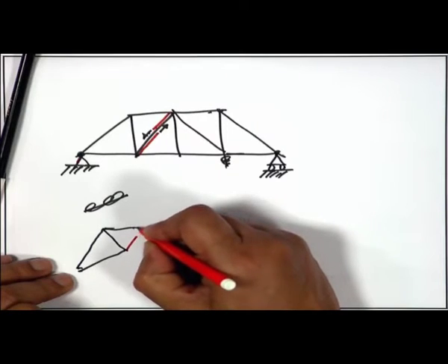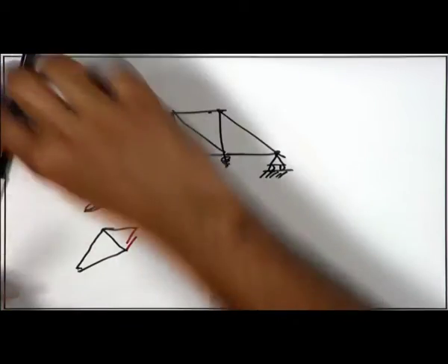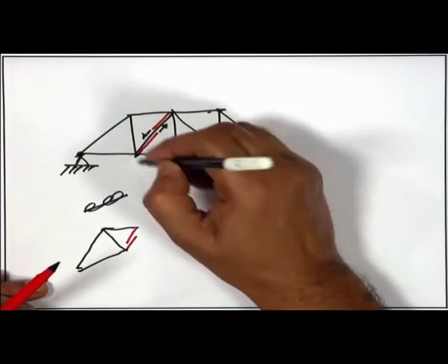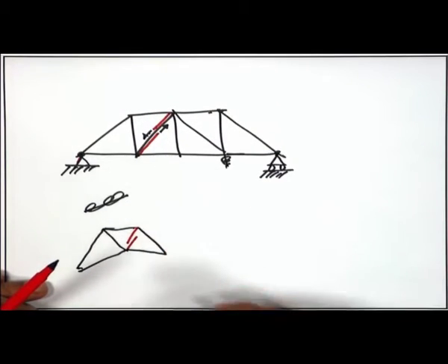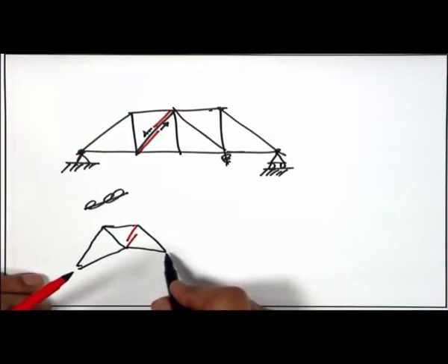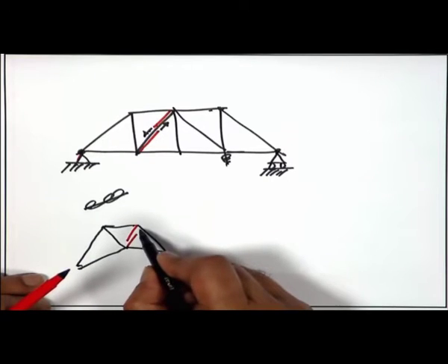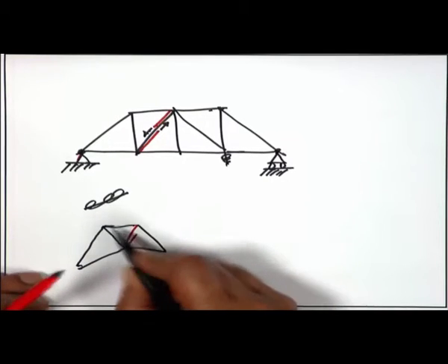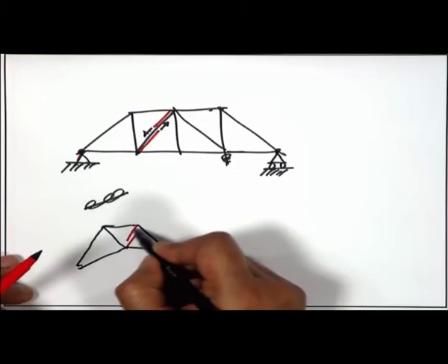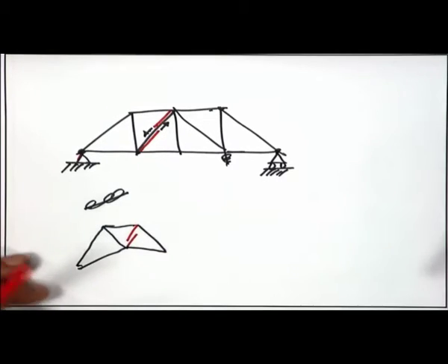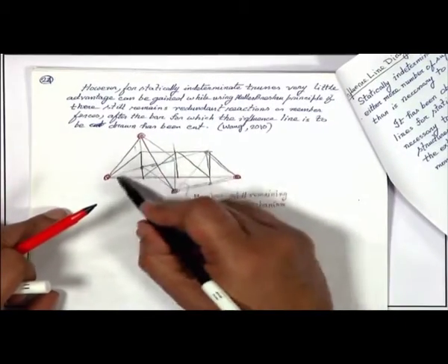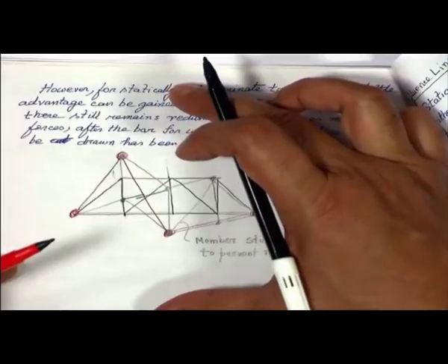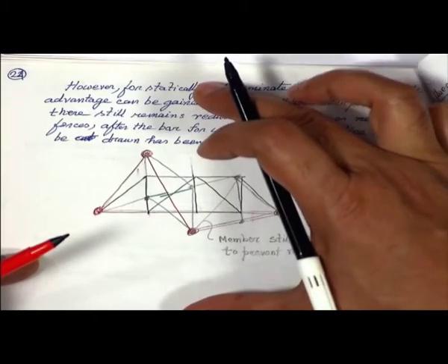Let me draw with an overlap. The portion which was a nice rectangle or a square will now become rhombic. If it becomes rhombic, it has to be deformed. So, this portion will go up. My drawing is not proper; I am showing you my original drawing which I have given to you. You can see this particular figure; I am explaining the Muller-Breslau principle to the students.